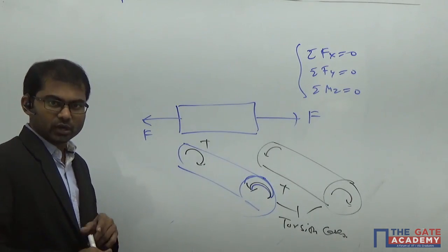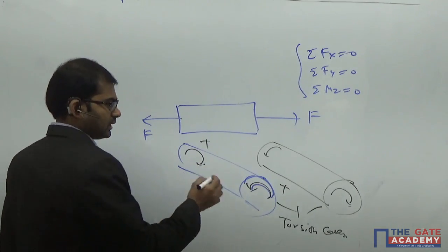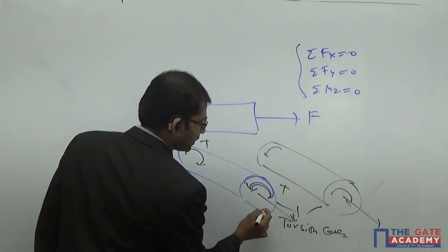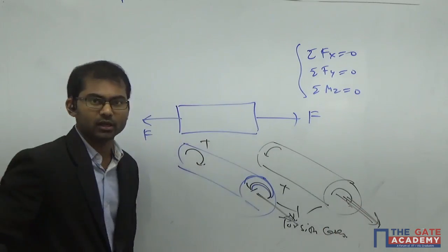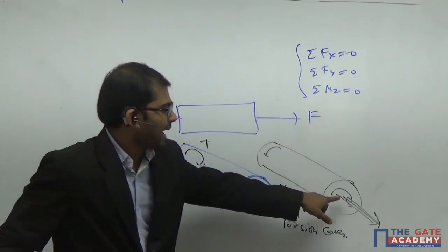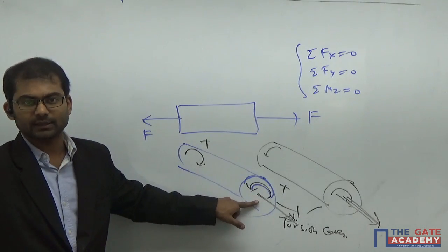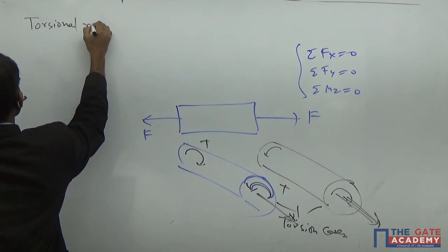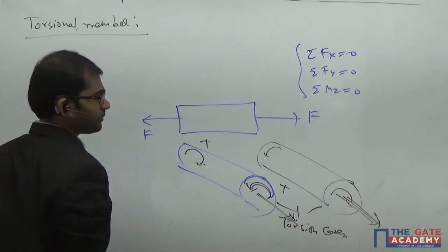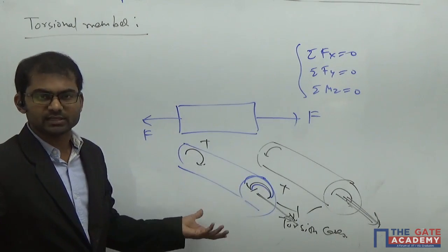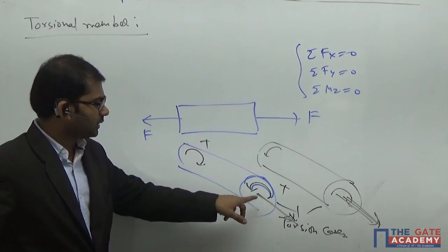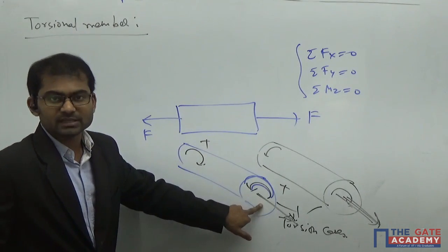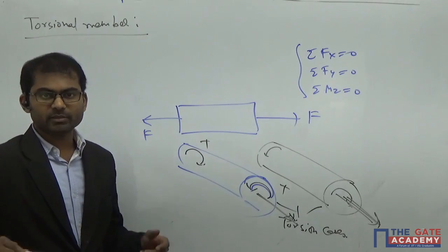Understand? Another thing you have to always remember is that this is the length direction, or x direction, or longitudinal direction. So both of these arrow marks are longitudinal directions. To create torsion, the moment must be acting about the longitudinal axis. A torsional member may not be a shaft, or a rectangular section or any particular section, but if it is experiencing a turning moment about the x-axis, the longitudinal axis, we call this member a torsional member.